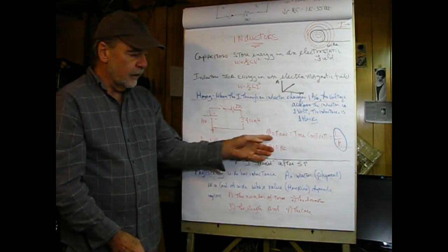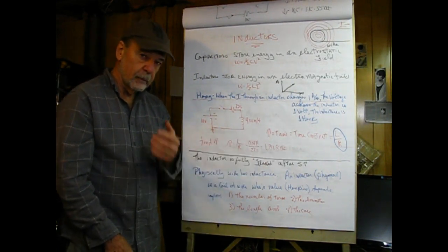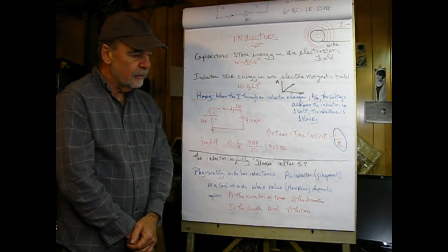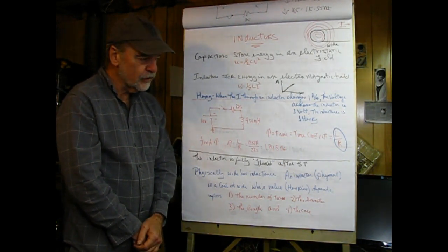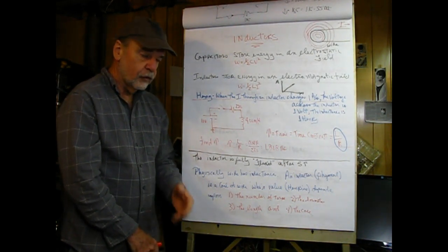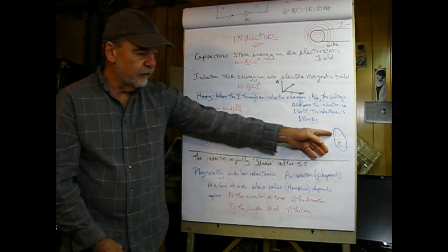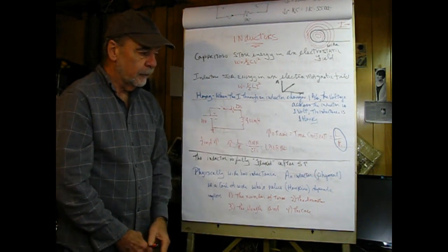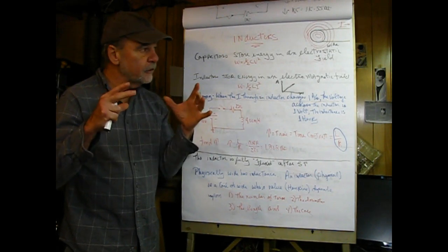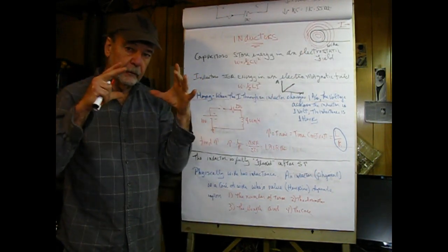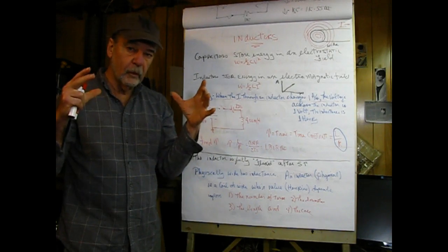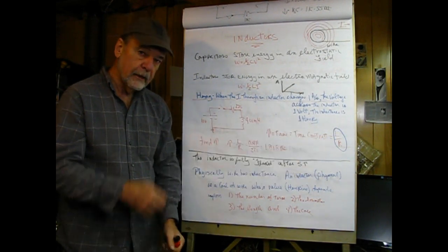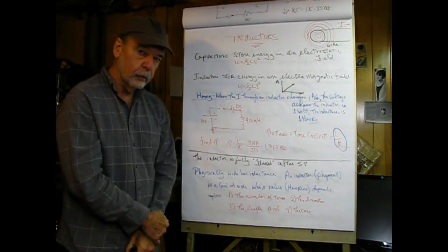The time constant, again tau, and again the unit is seconds, is equal to the inductance divided by the resistance. That may seem to be a strange relationship, and a little more challenging to understand than the RC circuit. If we had an inductor of, say, a Henry, and a very, very small resistance R, with a time constant of 1 second, then in your mind's eye picture this magnetic field collapsing and being 66% of what it would be in 1 whole second. So it slows down as R gets smaller. The collapse of a field would slow down.